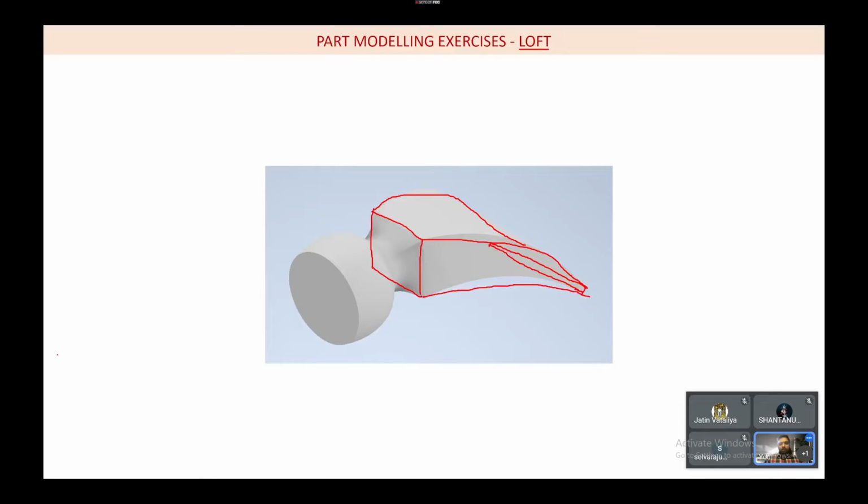So let me go to sketch here. I'm going to create an edge. I'll switch on the construction and draw the line, and I'll get some horizontal line randomly. So you can see there is a line which I have drawn, and now I am going to draw another line in construction mode from this point, perpendicular.